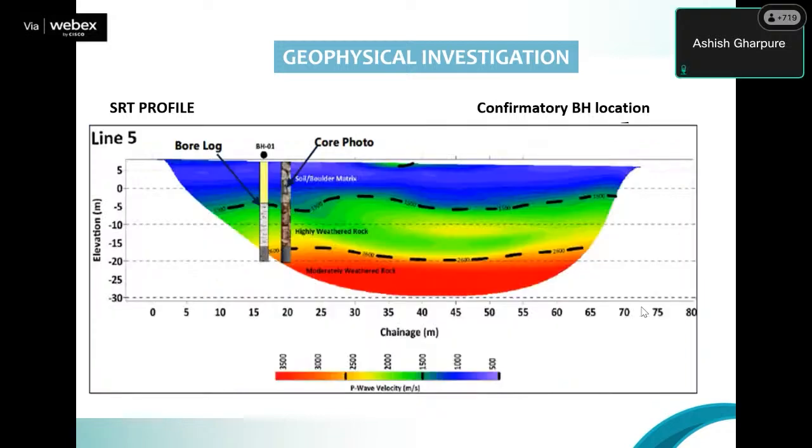Yeah, so you can always then cross check. I would again caution that geophysical methods are qualitative. But it will give a very good idea whether the substrata is uniform or disturbed, and then you can actually pick and choose the points to do borehole surveys. But it's always good to do borehole surveys and then corroborate the results of either the borehole and SRT, so that you know your layers pretty sure.